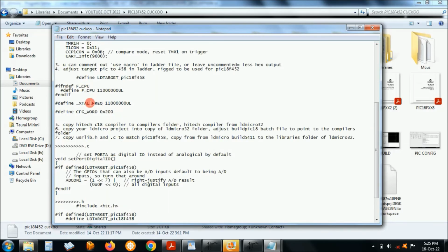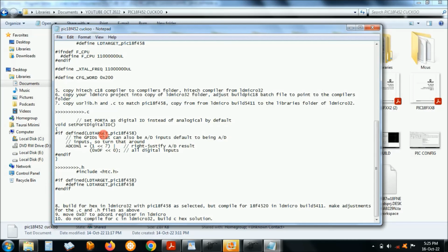After changing the PIC target, you also have to change here, but that wasn't working, so I had to force a load of 7 into the special function register, and it only does it once, when the program starts.